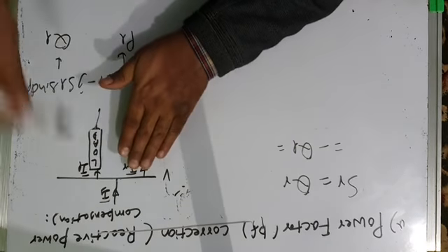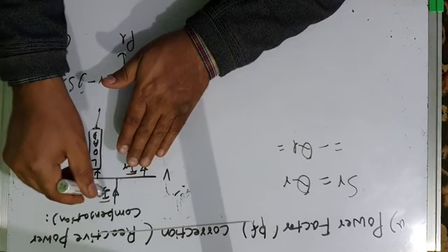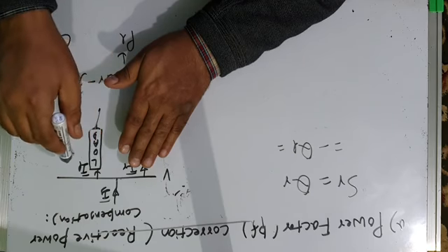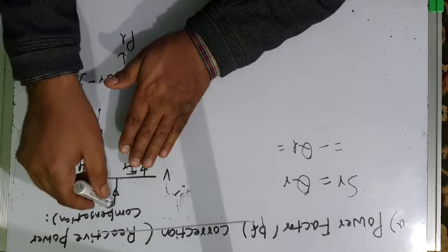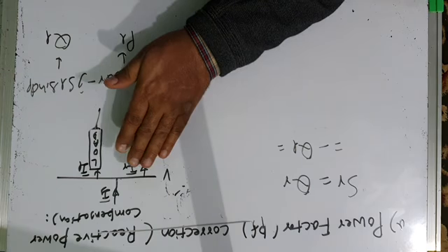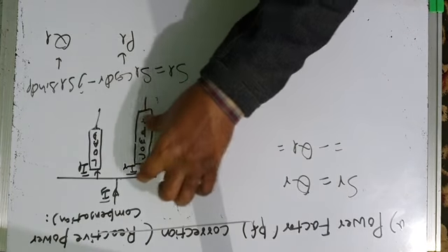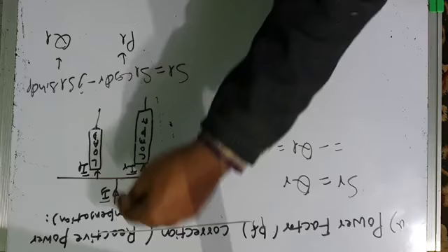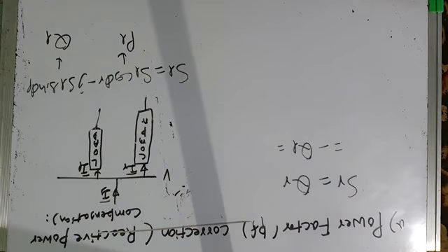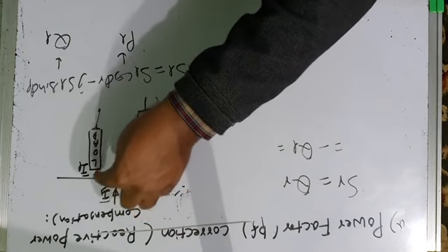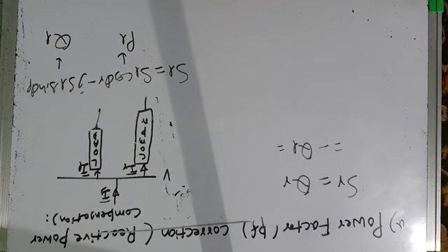जब कंपनसेटर नहीं था, वो रिएक्टिव पावर भी सोर्स से आता था. उससे सोर्स करंट लैग करती थी वोल्टेज को बाय सर्टेन एंगल, और पावर फैक्टर लेस देन यूनिटी बन जाता था. That is, the source was supplying not only active power at that time, it was supplying reactive power also. But now when you connect the shunt compensator across the load, it is the job of this compensator to supply the reactive power, whereas only active power should come from the source, and active power coming from the source means that the source current is in phase with the voltage, so power factor becomes unity, 1.0.